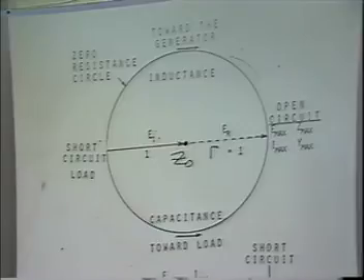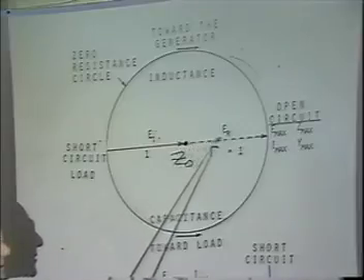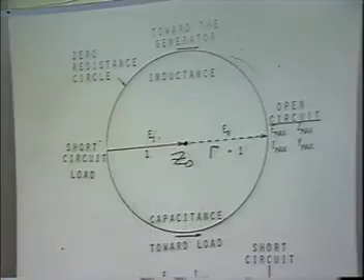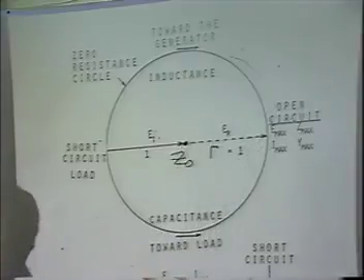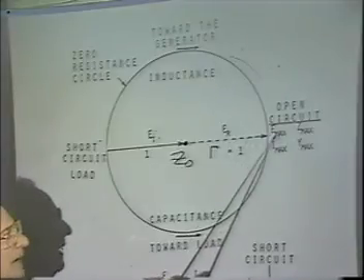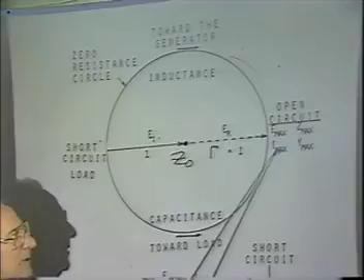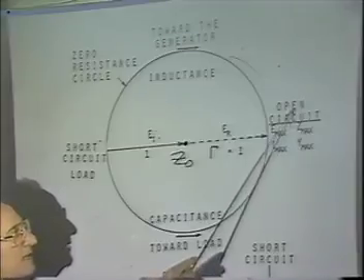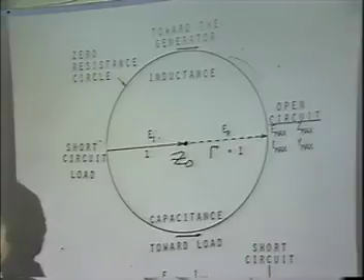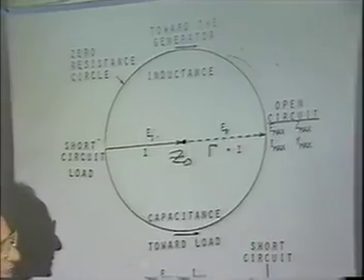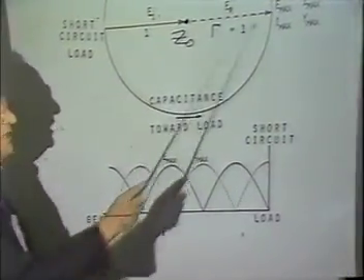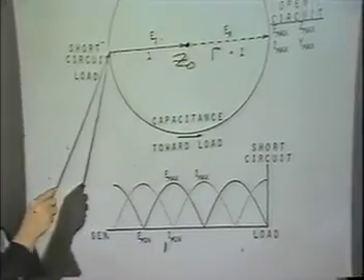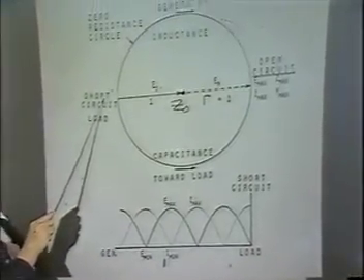We know then that any time we're on this line here, along this direction, this point here, we have a pure resistance that is greater than Z0. And notice something about this axis out here at the open circuit. We know that the voltage is maximum, the impedance is maximum. Now, when you say current is maximum, that's not maximum for an open circuit, is it? Because look, here's an open circuit, voltage is maximum, what's the current? 0. Right? But notice, if the voltage is maximum up here, where's the current? The current is minimum over here, isn't it?